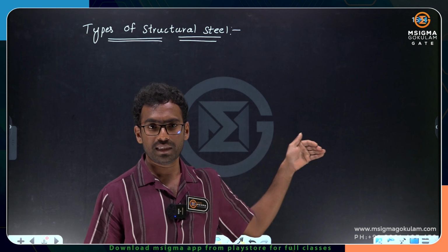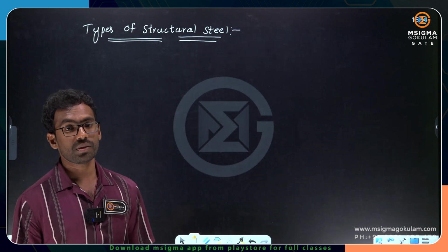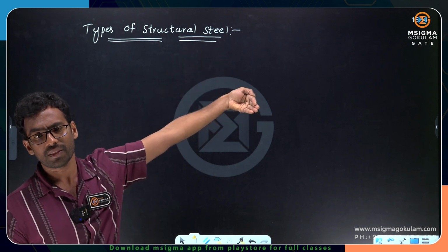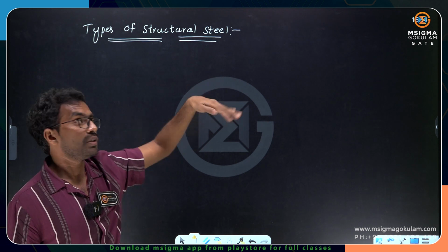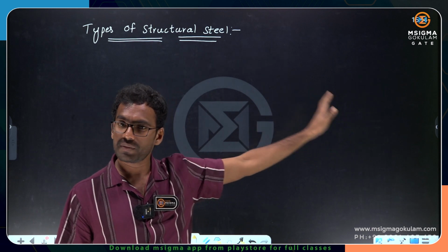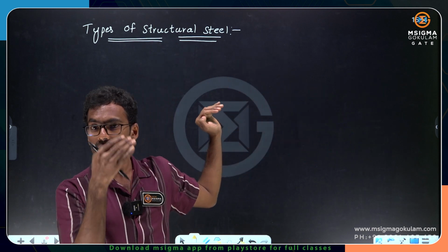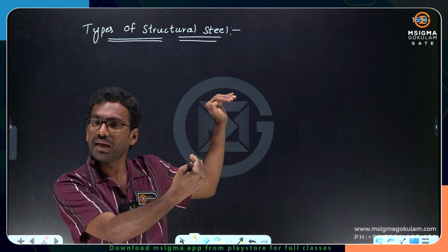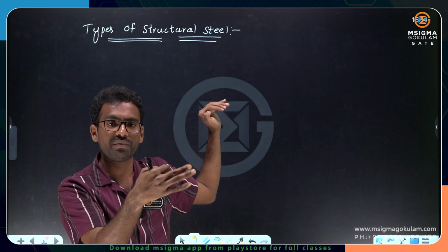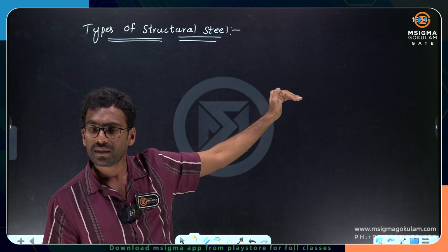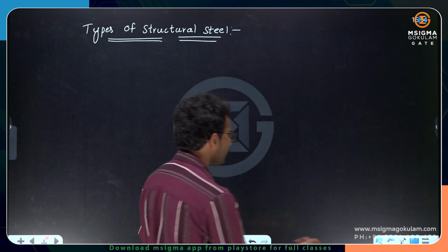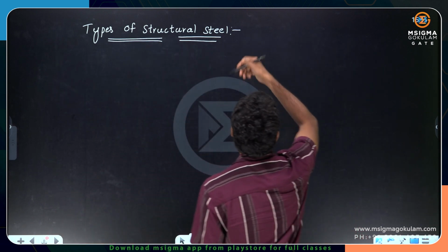Now, coming to structural steel, what are the different types of structural steels? Structural steels are the steels which we are specifically using for steel structure construction. Okay? Very important thing, please understand, don't get confused, because I am saying this clearly in order to differentiate reinforced concrete structures from steel structures, I am giving examples of both. So, reinforcing steels, we have the category mild steel, HYSD, TMT, and in HYSD, TMT 2 grades, 415, 500. That means reinforcing steels are represented by their yield strength. When I say mild steel, typically, okay, so I'll come to this point later.